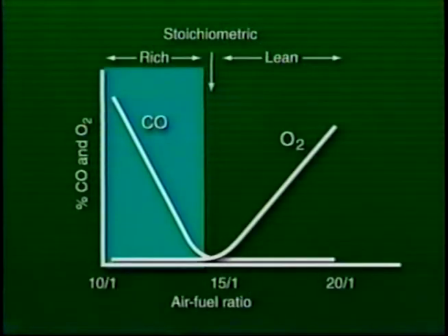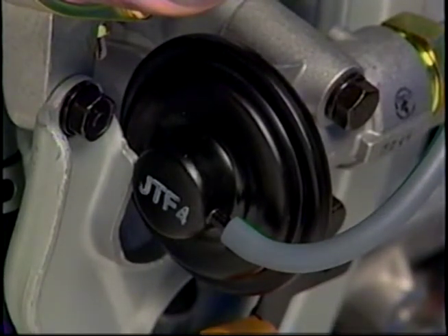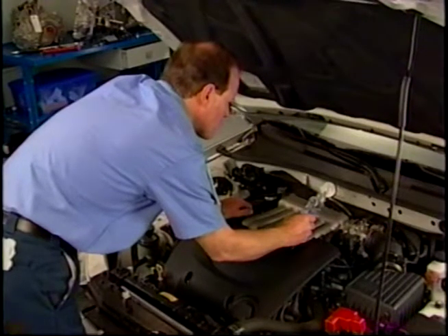High CO readings result from rich mixtures. High NOx emissions result from high combustion chamber temperature. An inoperative EGR valve is the most likely cause, but don't overlook engine overheating. The EGR valve can be checked by different methods depending on whether it is vacuum or electrically controlled.